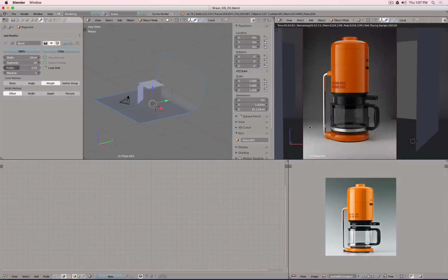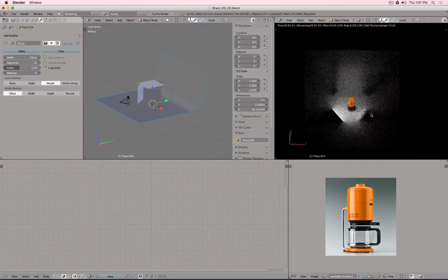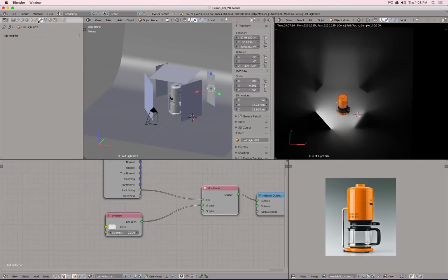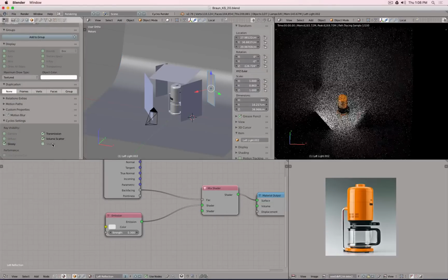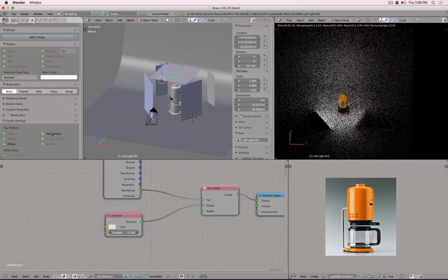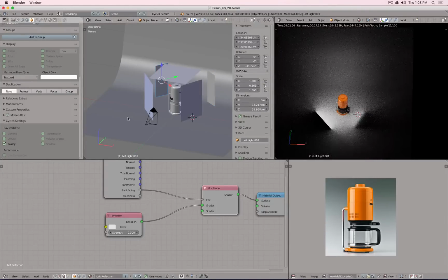And yeah, so what do we have? Maybe let's zoom out for a moment, because I see some shadows that are happening, and my objects that create a light reflection are casting shadows, nothing I want. So I select these objects and say also don't cast shadows. And now they don't interfere with my backdrop.